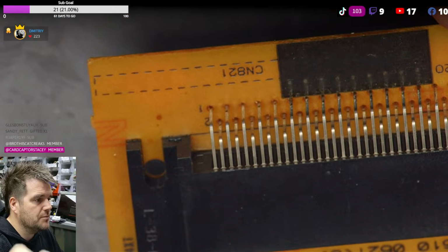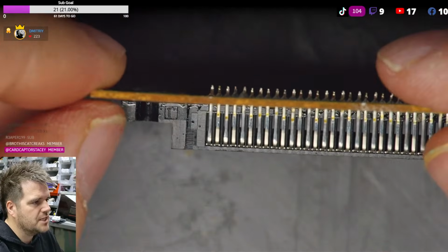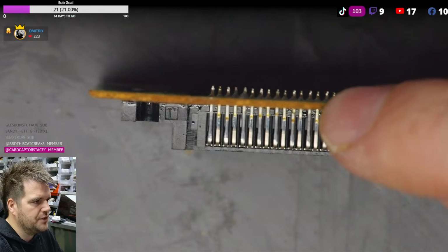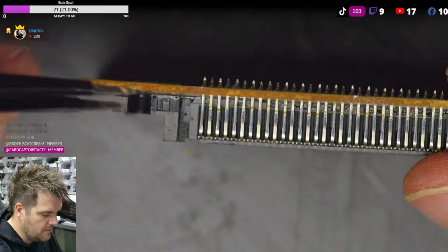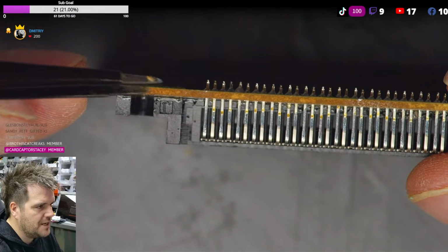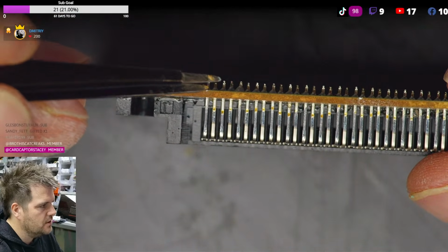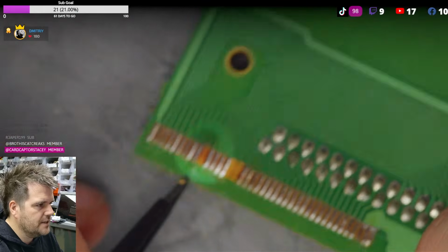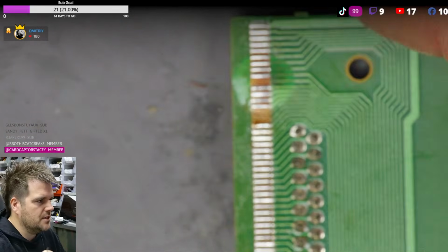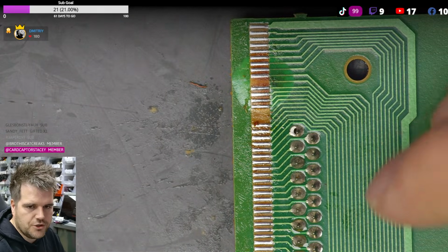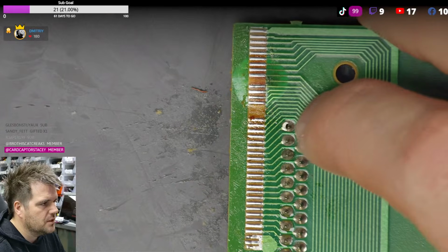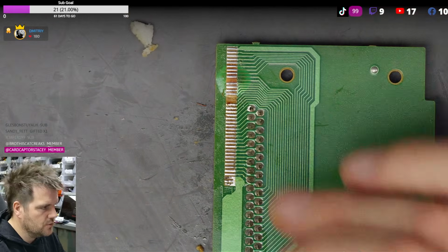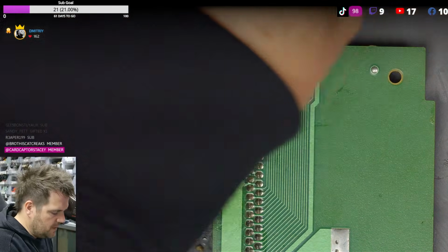Because this is a paper PCB, these bright orange PCBs are basically, for the most part, just compressed paper. You might as well think of them as paper with a bit of bonding glue in. So fluid can get inside here and penetrate very easy. So see all these dark orange bits versus the lighter orange, that's fluid that's got in near the edge and causes that. So again, not the end of the world, it's fully functional, but we've got 3 pads to restore when we're done, and a connector to put on.